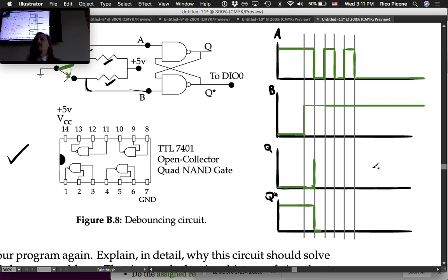It essentially uses the fact, and the one thing I do want to say is, when you work through this last little move, what you find is that for the first time, this is one of the simplest circuits where there's memory involved. So A going from low to high the second time doesn't matter. It only doesn't matter because this double NAND gate introduces memory into this circuit. It knows what the previous state was, which is weird, because the NAND gates alone don't care. They're continuously updating. But when you connect them like this, they actually have a memory for how the signal changed.